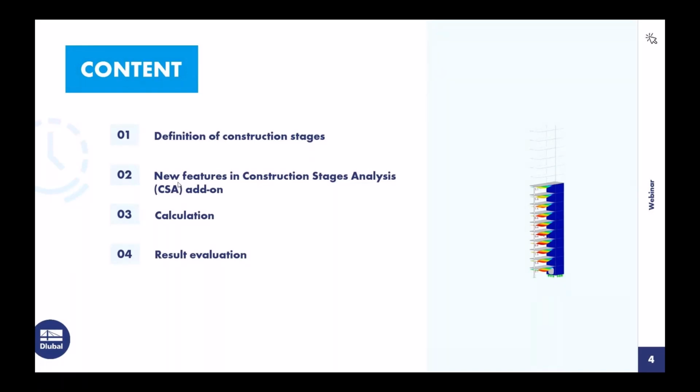I will show three different examples. One quite simple example in the beginning, to show some basic principles of the construction stages analysis in combination with the time-dependent analysis, especially regarding long-term deflection or long-term behavior regarding creeping.